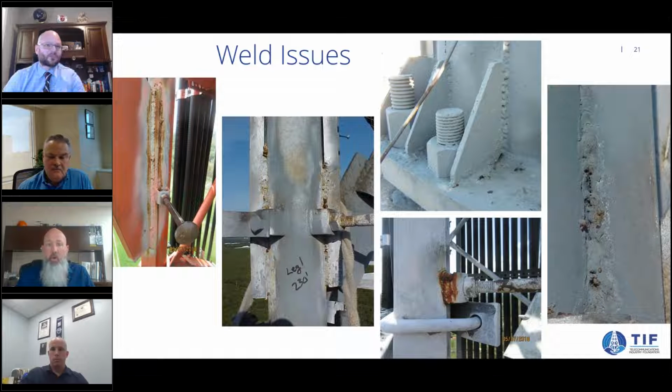And this is where it really goes to be critical to have a PMI done when we're doing any kind of modifications to a structure. A good PMI would have caught these issues pretty much immediately after the structural modification had been completed, and we wouldn't have had to wait until a maintenance condition assessment cycle came around to find these problems.